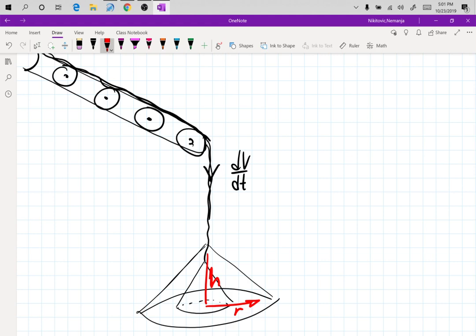We want to make sure that the machine will shut off before the cone reaches the conveyor belt, because if the cone reaches the conveyor belt, the stuff will fall onto one side of the cone. It will accumulate on the conveyor belt, and it will eventually break. The weight of the stuff on the conveyor belt will break the conveyor belt, and those things are very expensive.